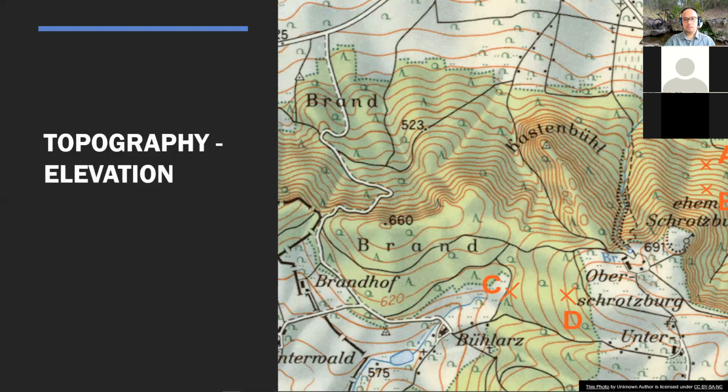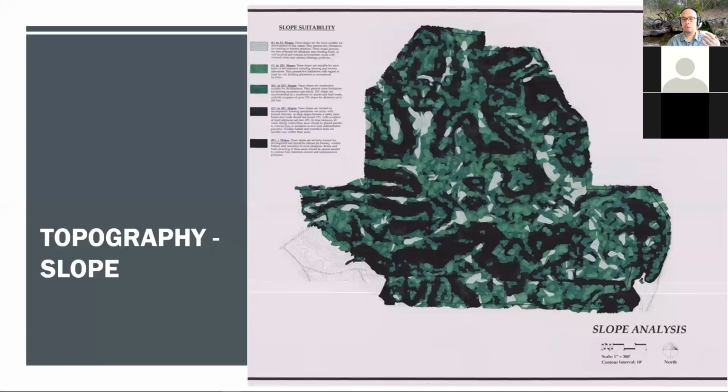And then this choropleth, once you've got the contour map and the elevation lines and you colored it in, produced a choropleth map, then this combination of information would give you an idea of the different slopes. So a site's suitability for roads, walkways, buildings, and other structures is, in part, a function of the existing slopes on the site.